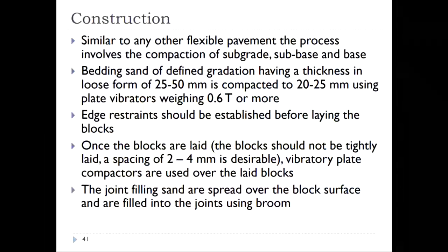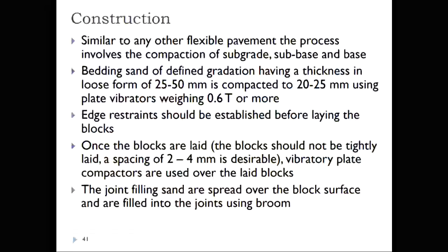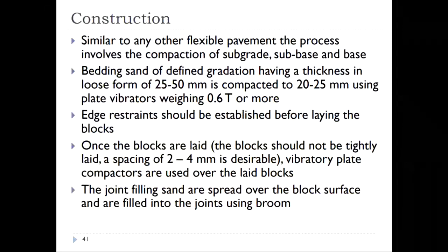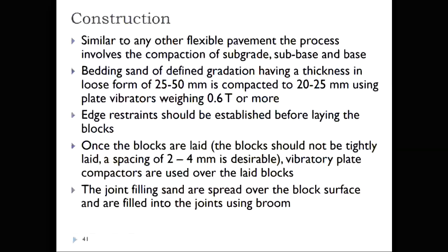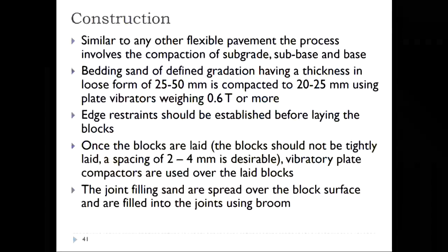Now coming to the construction aspect. Here we also discussed the design aspect and the composition aspect. Now, the composition aspect here: your concrete blocks are provided by the manufacturer, so we are concerned about the strength of concrete. The other material aspects in the case of your interlocking block pavements are the gradation of your bedding sand and your filling sand.